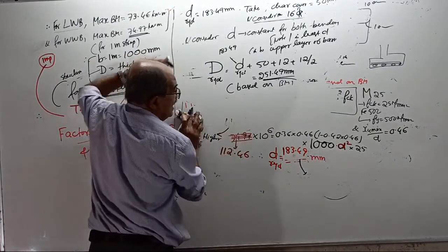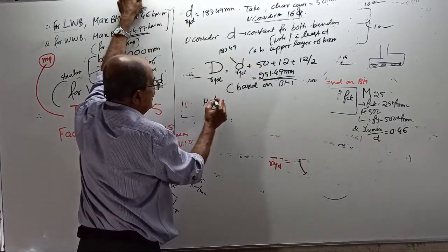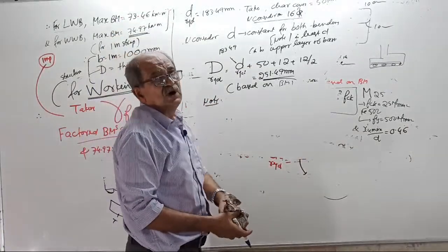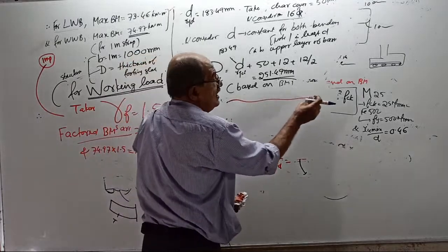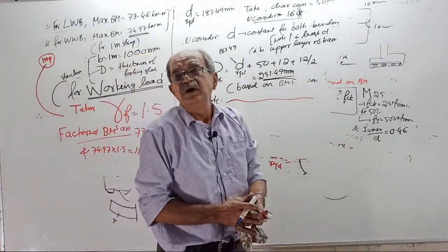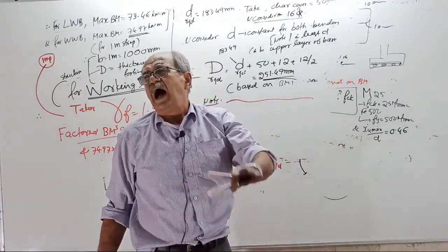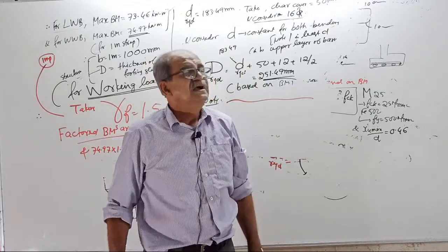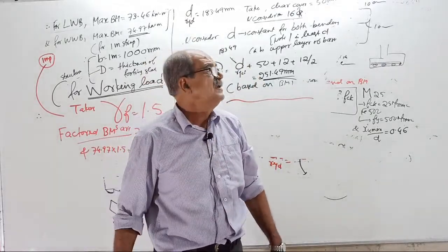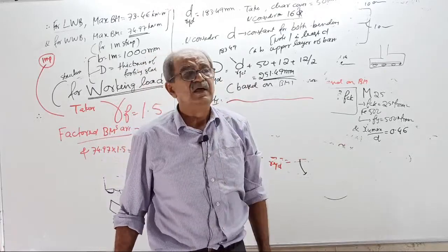Now write a note here. I am dictating, you write it. In case of footing slab, if you provide the depth based on bending, I am sure it is going to be 100% unsafe. It is not sufficient because for footing, shear is very, very critical.